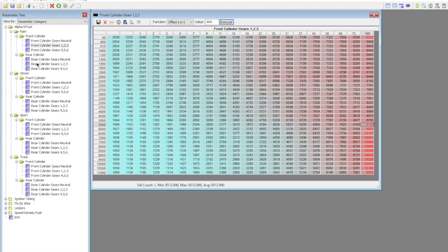So these exhaust extraction kits are really cool. Basically, you drill a small little hole in a runner. You press in this little threaded rivnut. You temporarily screw in a little metal adapter, which then you screw your wideband O2 sensor into. So it reads each cylinder individually, and then you can tune each cylinder individually, and you'll find you can pick up 5% more power by tuning each cylinder individually versus just doing the gross average cylinder tuning method, which a lot of people do.